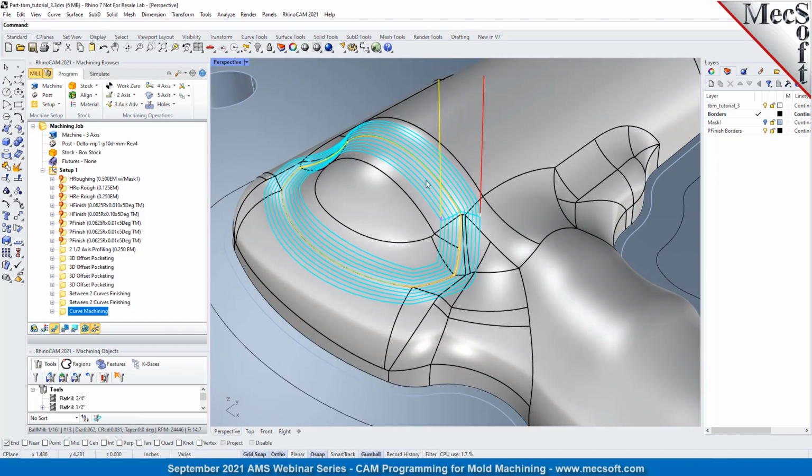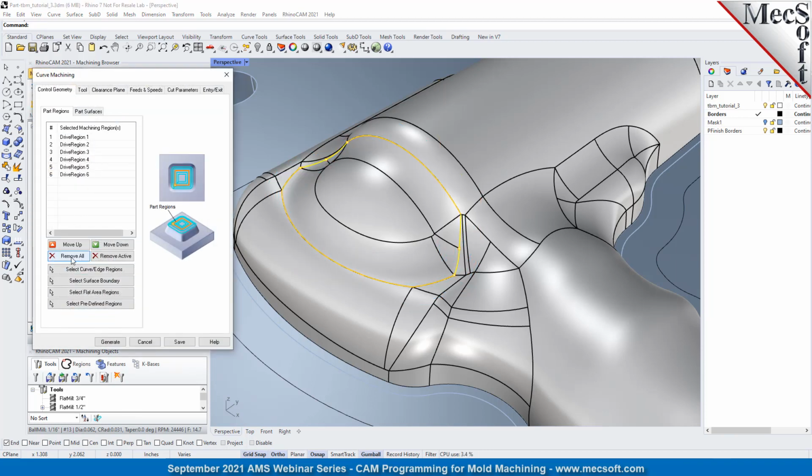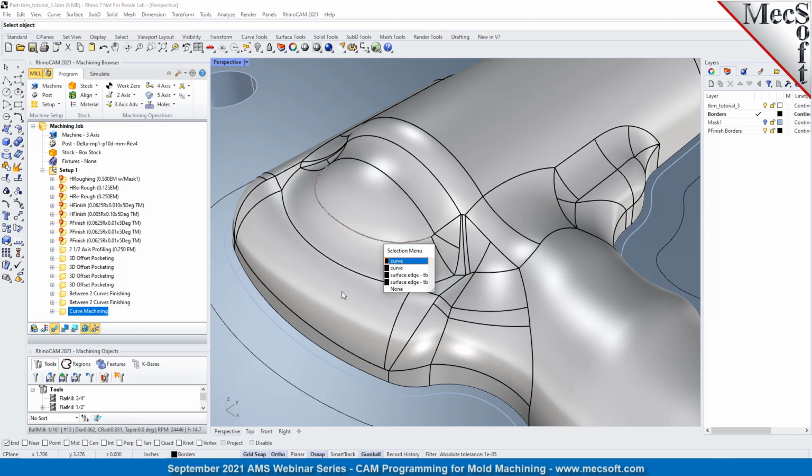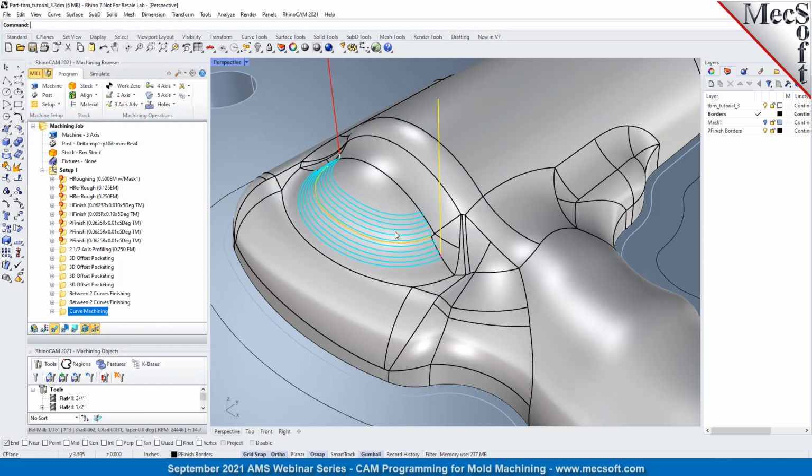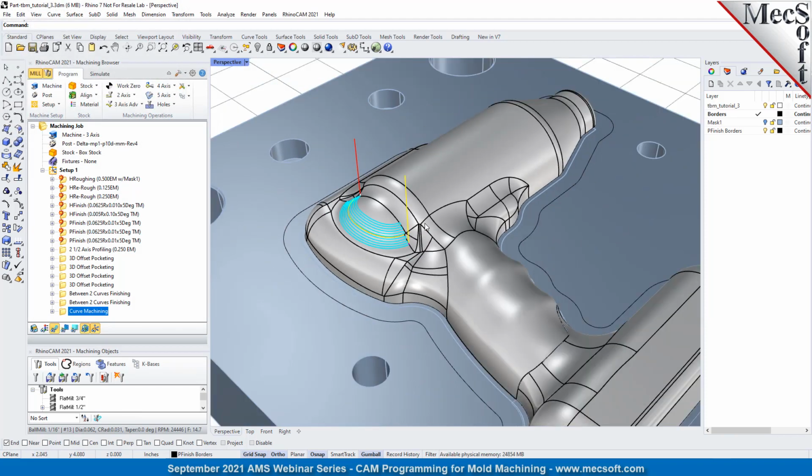Okay, so you've got a three-dimensional toolpath that's following the selected curves that we created, and it steps over 20 thousandths, and there's a total bandwidth of 0.1 on either side. So you can use this to do touch-ups in certain areas of the part, and all you need is a curve. And you don't have to have a closed curve. You can remove those and just have one single curve and generate that. So you can use that for all different kinds of cleanup operations.